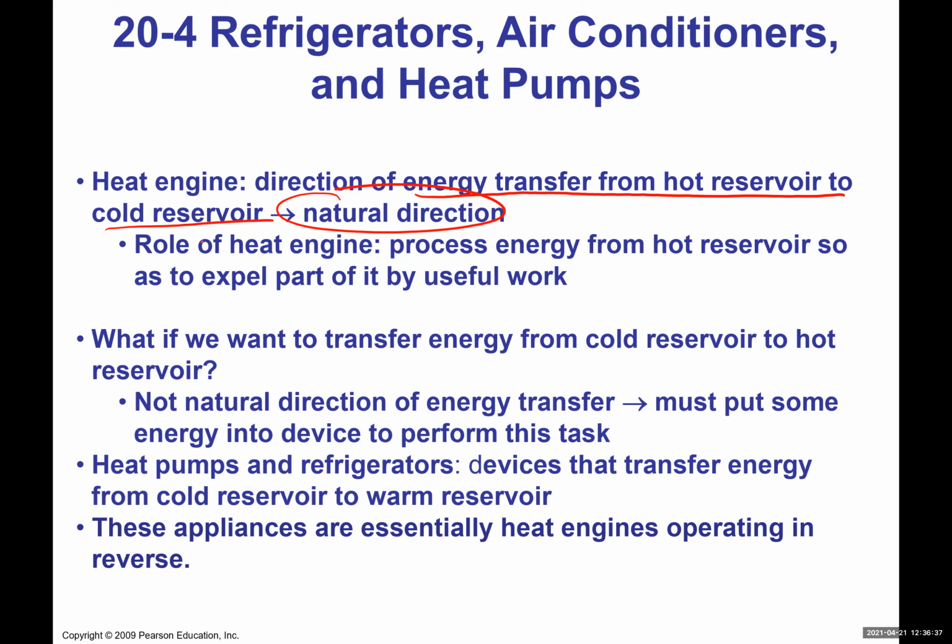And heat engines are useful because we can always extract some of that energy into useful work. We saw that theoretically you can never have a 100% efficient heat engine. Most of the energy technically ends up being dumped out. So there's a theoretical maximum efficiency, and in practice, if we try to build any heat engine, we can never even reach that theoretical efficiency. We are always about 60 to 80% of that theoretical efficiency.